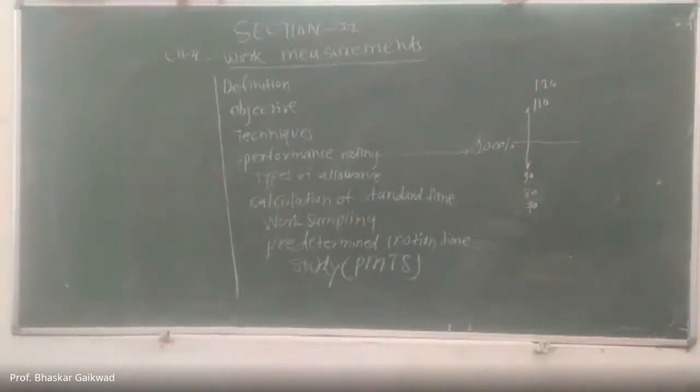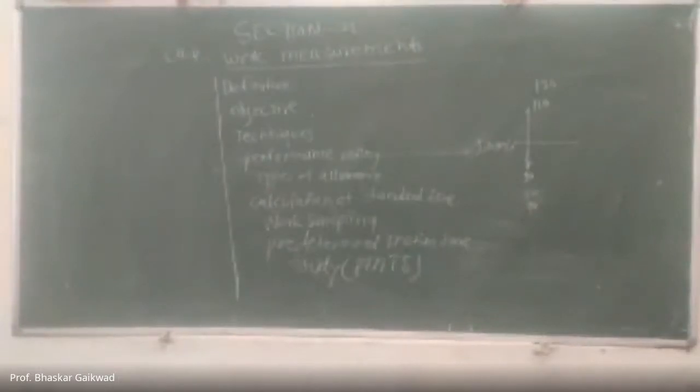That you have to observe. By using the stopwatch methods, we can observe this time. This observed time, multiplied by your performance rating, will give a normal time. Once again, I will repeat, while making the study in industry